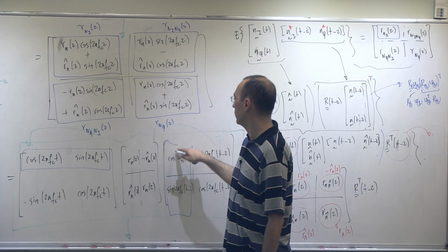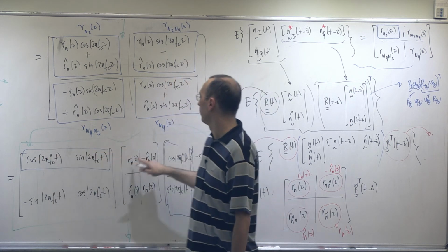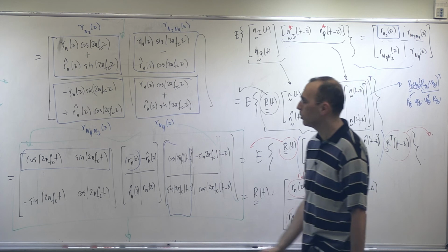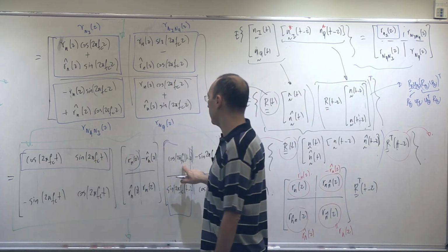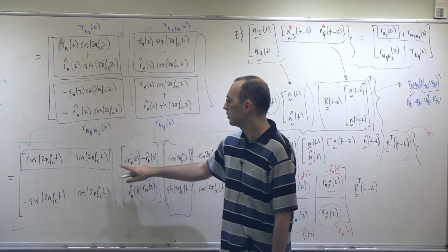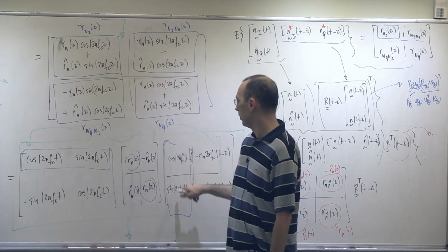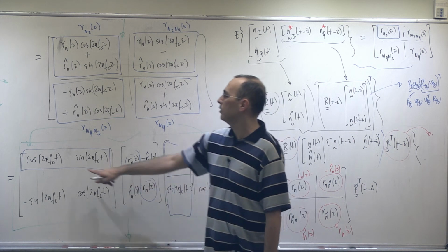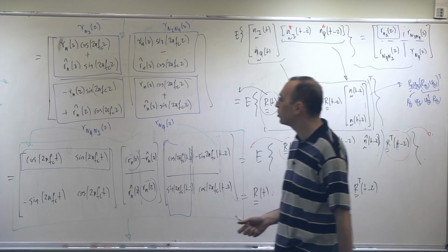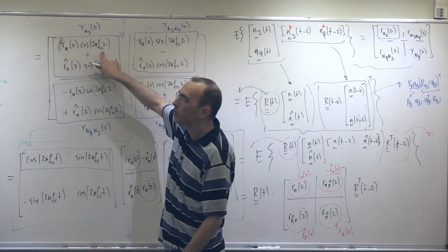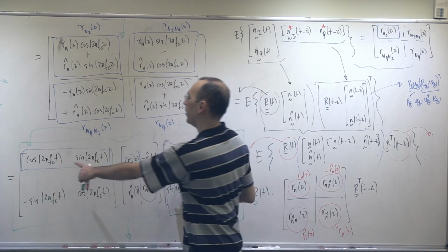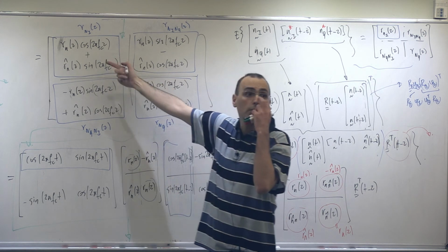So this A matrix times B. I'm interested in this inner product, this matrix times this. So about the coefficient of Rn of tau? Of course, this requires more exercise in linear algebra, but the coefficient of Rn of tau is this times that. So pull Rn of tau into common brackets. You have cos this, cos that, plus sine this, sine that. This is cos of this minus that. Do you see what I mean? Cos expansion. If you do this product, you will see. This minus that part is 2 pi fc tau. That is how you get that cancellation.